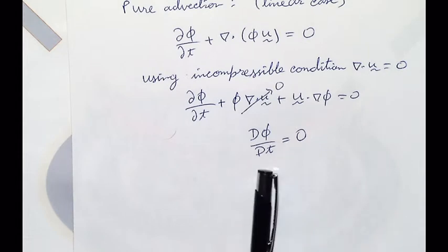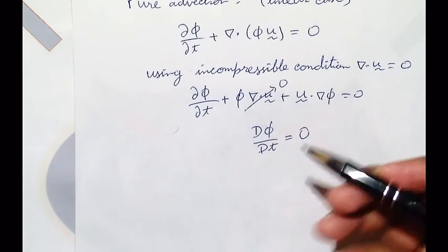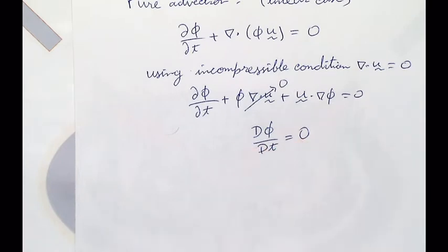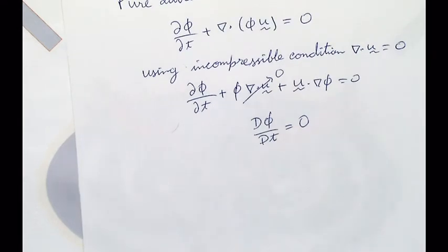Physically, do you remember what the material derivative indicates, in terms of a blob of fluid? The mass doesn't change. Yeah, so if my phi here, the general variable, is rho, the density, then this would be continuity, d rho by dt equals 0, which again goes back to it being incompressible.